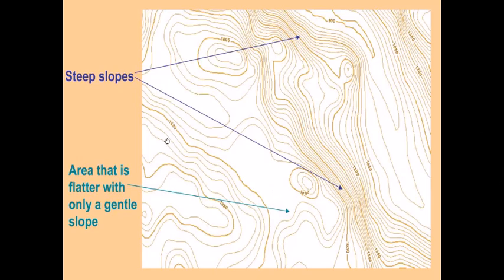And another thing to see is that some contour lines are bolder. We talked about this. These are called index contours, the contours on which you mark down the elevations. And then the contour lines between two index contours have elevations midway. And depending on the difference between the two index contours and how many lines you have, you can find out the contour interval, which is the difference in elevation between two successive contour lines.